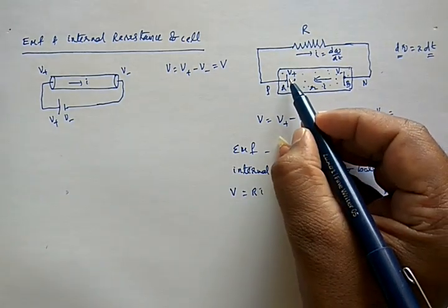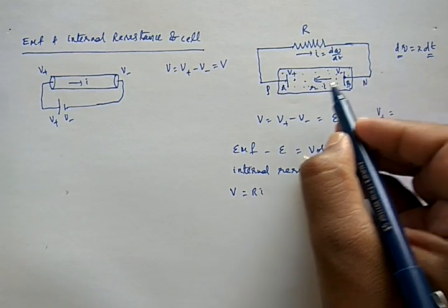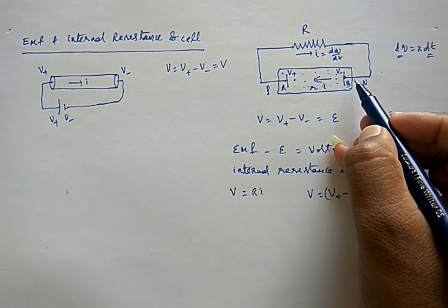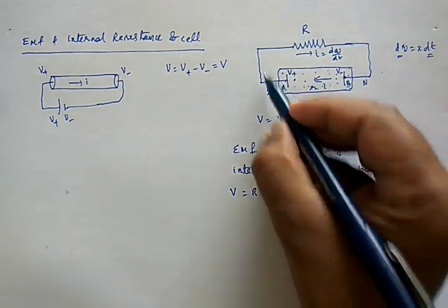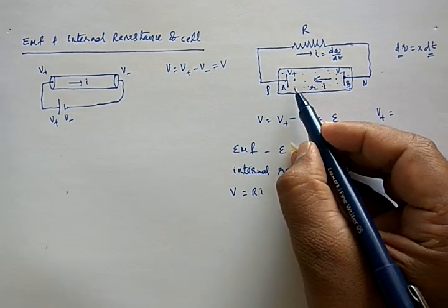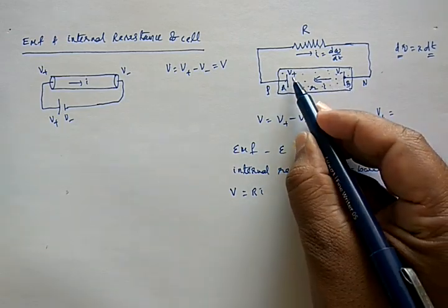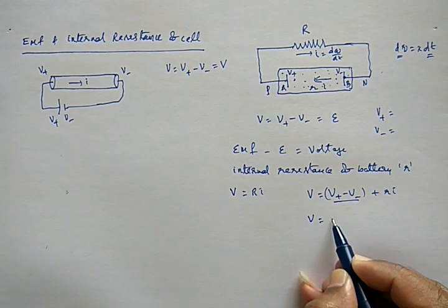So voltage across these terminals in this direction is Va minus Vb, that equals V plus minus V minus, which equals Ri. And when you compute the same voltage across the two terminals in this case, you get V plus minus V minus, that is what your E is.